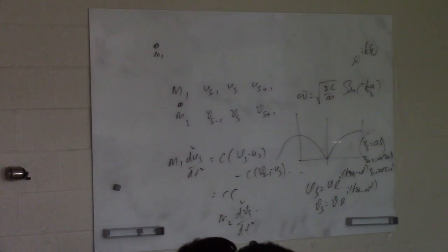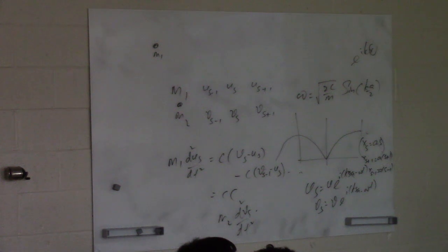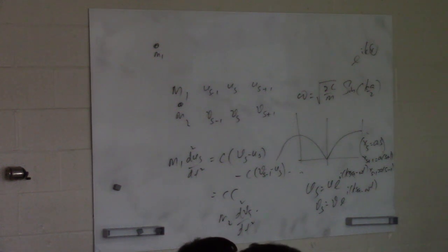So if you want to solve for u and v, then you can go back and show what u and v are. Yes. So if you do this one, that's the determinant. You can see where you get this term here. This one has 2c. If you take u, I have 2c minus m1 omega squared, right? This one, u, v has c times 1 plus this one. Again, v has 2c minus m2 omega squared. That's the determinant, right?